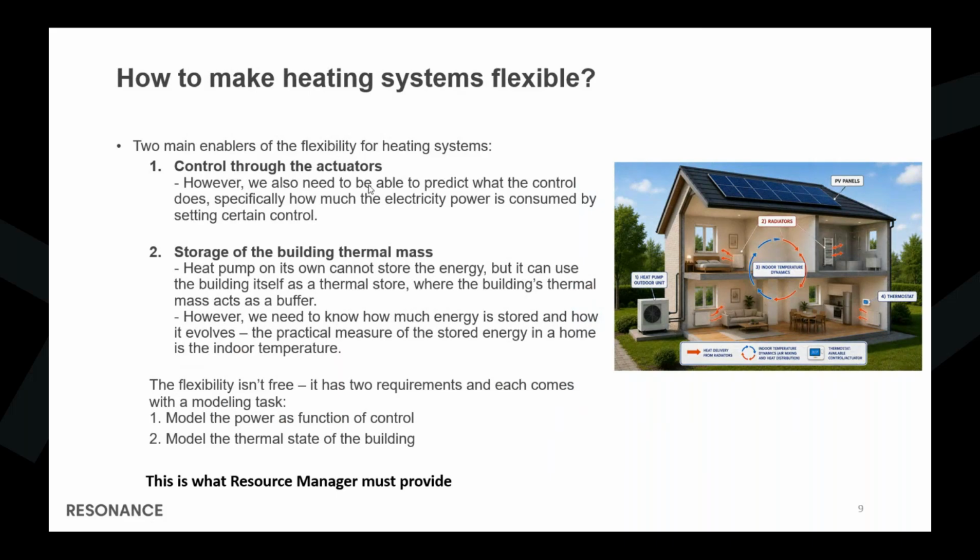We need to know how much energy is stored and how it evolves in the building. And the practical measure of that stored energy in the home is simply the indoor temperature. So to wrap it up, the flexibility isn't free. It has two requirements, and each one comes with a modeling task. The first task is modeling the power as a function of control, and the second task is modeling the thermal state of the building. And this is exactly what a resource manager of the heat pump must provide.